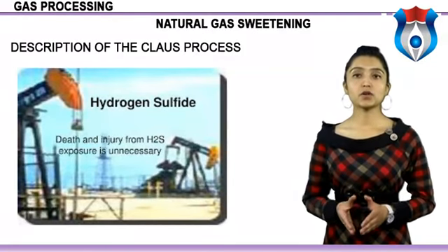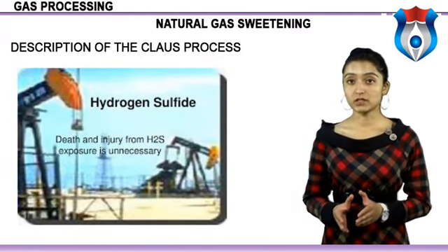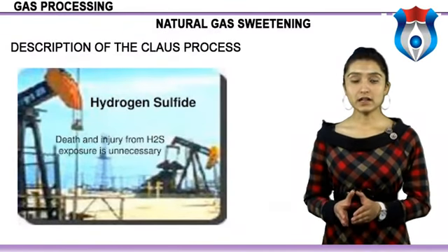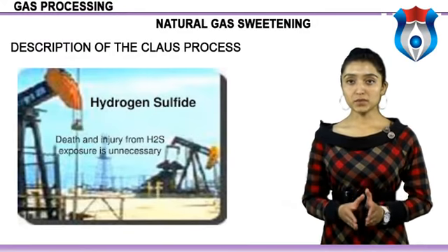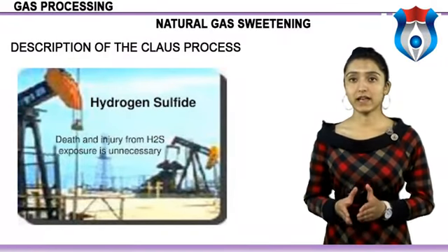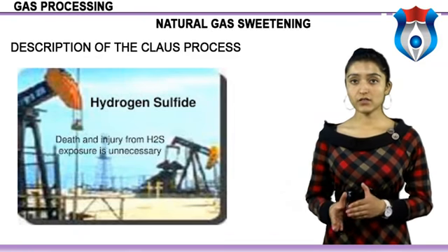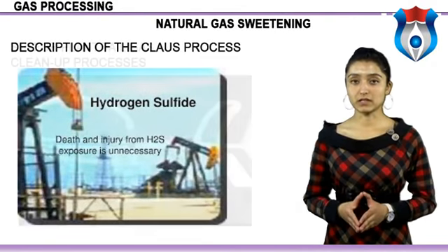Inevitably, a small amount of H2S remains in the tail gas. This residual quantity, together with other trace sulfur compounds, COS and CS2, formed in the burner side reaction, is usually dealt with in a tail gas unit. The latter can give overall sulfur recoveries of about 99.8%.